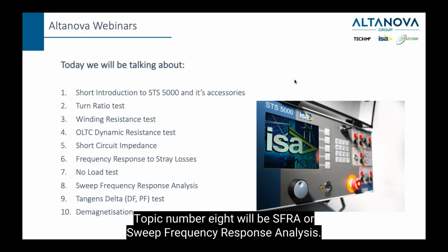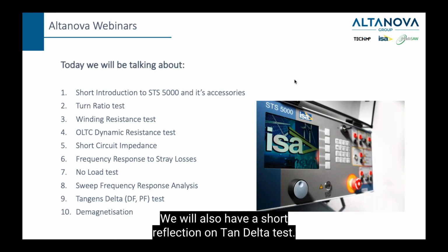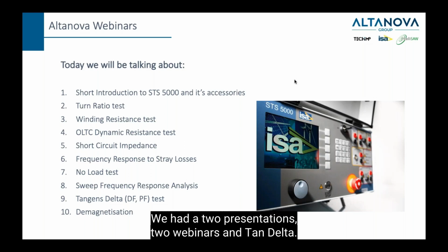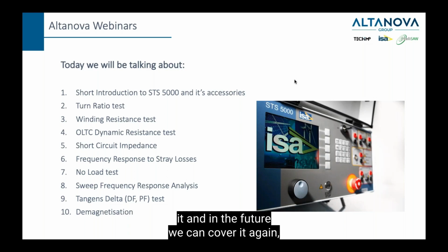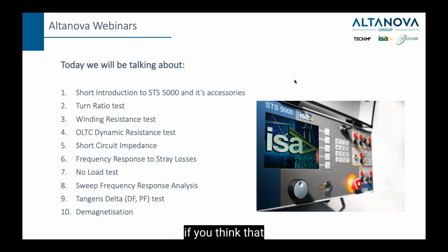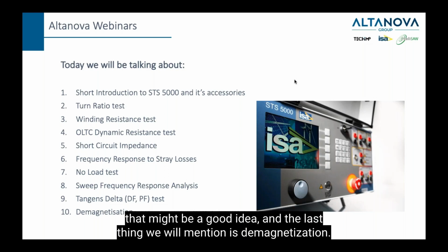Topic number 8 will be SFRA or sweep frequency response analysis. We will also have a short reflection on tan delta test. We had two webinars on tan delta, so we will not talk a lot about tan delta today, because we suppose that we covered it, and in the future we can cover it again if you think that might be a good idea. And the last thing we will mention is demagnetization.